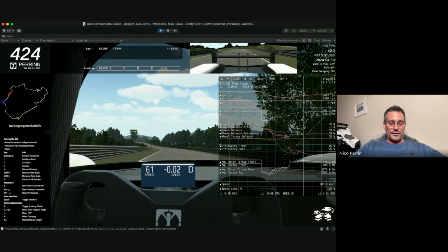We're going to 33%. Why? Because we have one motor at the front, two at the back. When we're at full power, full delivery, we basically use the motor capacity, and at that point we have a third of the power at the front, two-thirds at the rear.